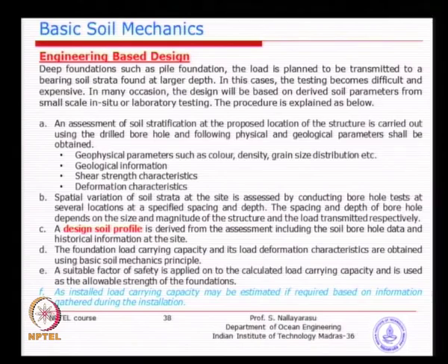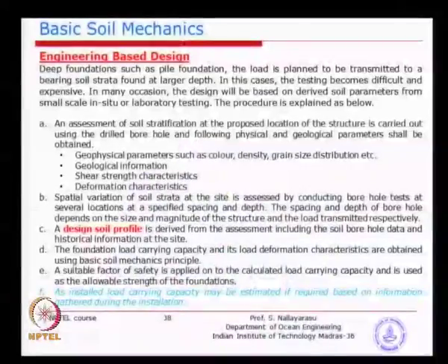But if you look at concrete piles or maybe other shallow foundations, different factors of safety, maybe they will allow 3, 4, sometimes some codes ask for 3. So, it depends on the uncertainties and the potential problem with failure, the risk of failure and type of structure. For residential buildings, you want to give a higher factor of safety, where the risk is higher for human life, whereas for low class structures where there is no human activity, you can actually reduce the factor of safety, because you are only going to lose the property, but not human life. So, the engineering based design is the one that we are going to practice.